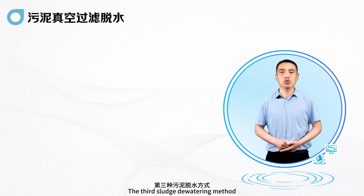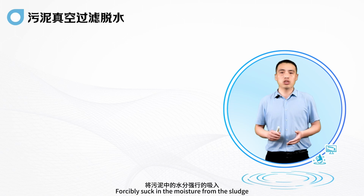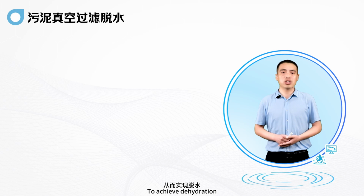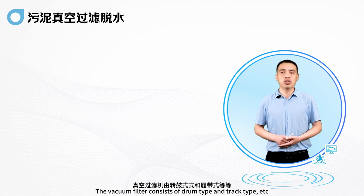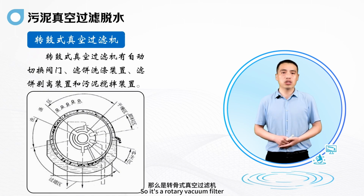The third sludge dewatering method uses vacuum filtration. Sludge is placed on a porous filter medium, and a vacuum is created on the other side of the medium, forcibly sucking the moisture out of the sludge and separating it from the sludge, to achieve dewatering. Vacuum filters include drum type and belt type, etc. For example, the image on the right is a rotary vacuum filter. This filter has an automatic switching valve, a filter cake washing device, a filter cake stripping device and a sludge mixing device.